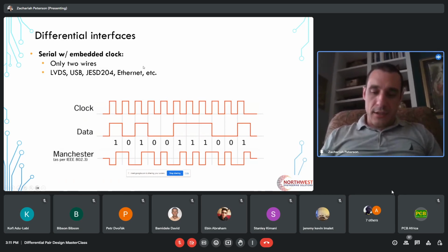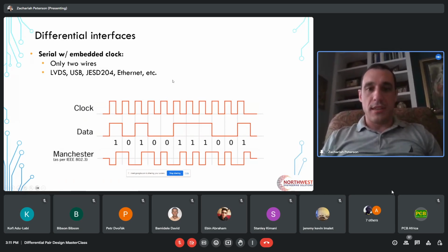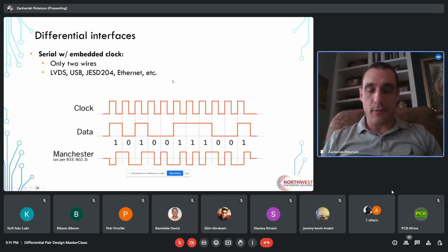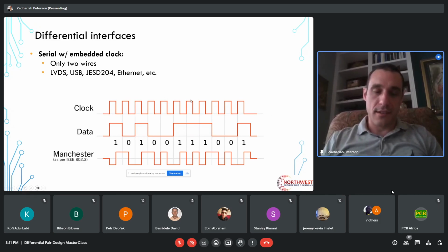So the signal speed is simply the speed, literally, at which the signal travels. But what's actually being contained in the signal? Well, the signal contains data, of course, and typically we don't have a separate clock in serial interfaces. The separate clock is a artifact, or not an artifact, but kind of left over from the days when we had system clocks or when everything was source synchronous. So if you are familiar with SPI, you'll know that SPI is source synchronous.